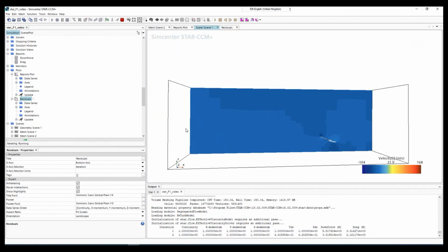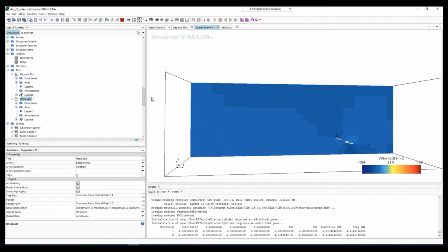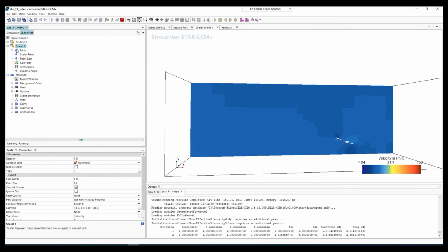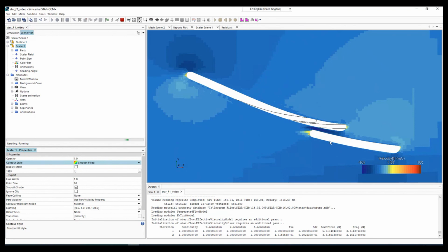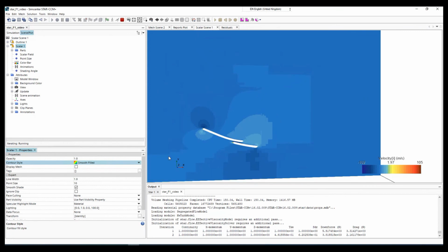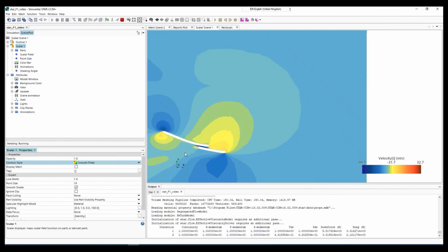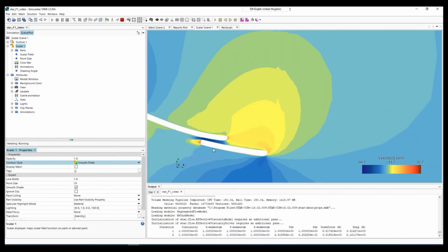And in the course, we can change the visualization in here. If we go to scalar and click scalar 1, which is x velocity, and we choose smooth, the contour will show up in a better way, smoother. It's a bit more mosaic now, but we can change it to a smooth one. Takes a bit longer to respond. Okay, so we will keep it running, and yeah, you see this is a smooth contour.